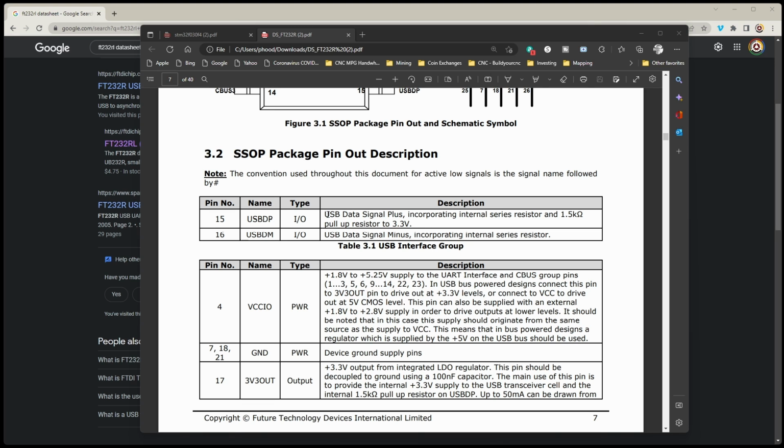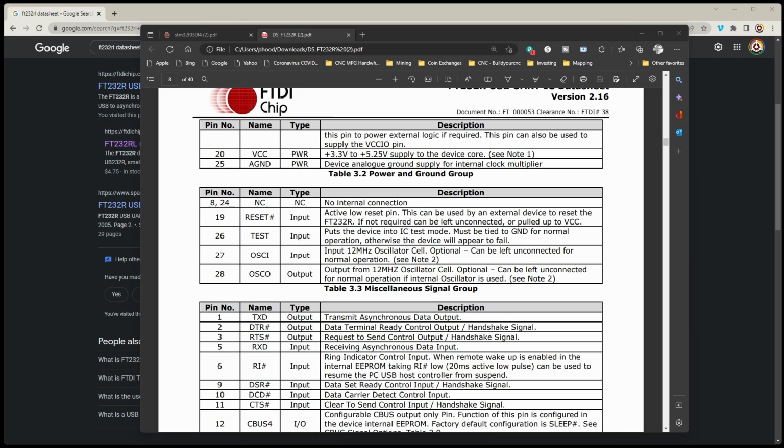Before you use this integrated circuit in the schematic, you want to make sure that you understand the function of each pin on the integrated circuit. There will probably be some very important information on each of these pins that you will need to know. Otherwise, you risk that part of the schematic not working. One such example on needing to understand each pin is there may be a requirement that it has to be either pulled up, connected to ground, or can be left unconnected.